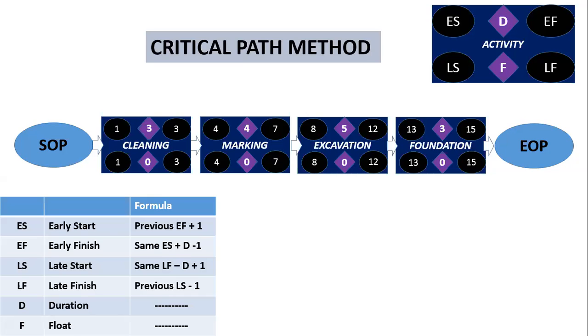Everyone getting it? Do you want me to repeat? No, sir. Then what is the late finish of the first task, cleaning? 4 minus 1 is equal to 3. Then what is the late start? 3 minus 3 plus 1, that is 1. Everyone comfortable with this cycle?